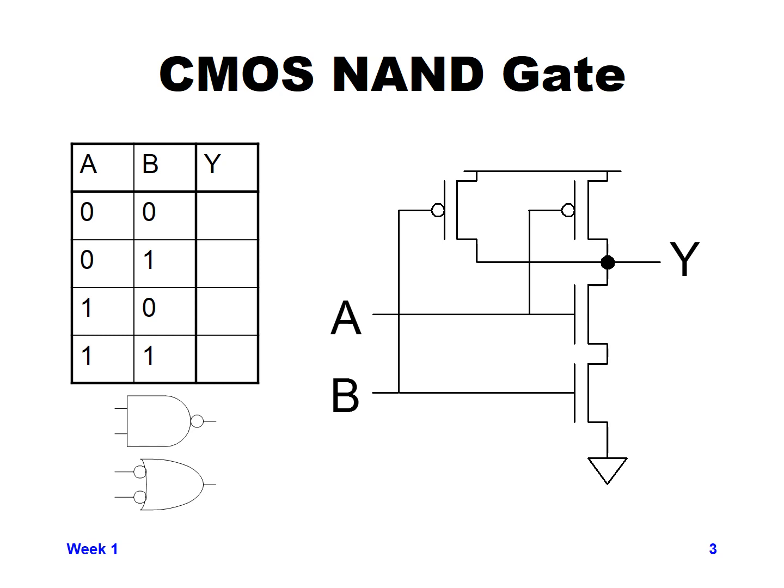But in this case, we'll see that we have 2 NMOS in series with each other. The source of one NMOS is connected to ground, the drain of that NMOS is connected to the source of the next NMOS in series, up to the output signal Y, and the 2 PMOS transistors are connected in parallel with both of their drains connected together to the output Y and both of their sources connected together, and that is connected to VCC.